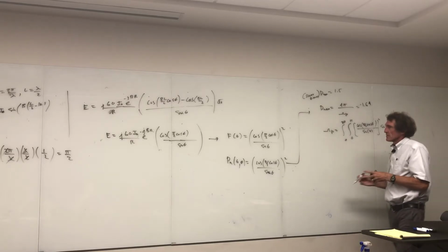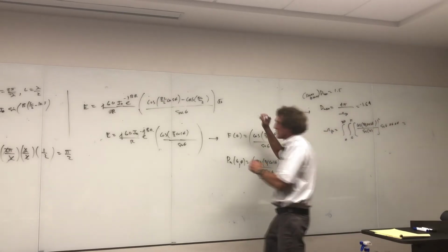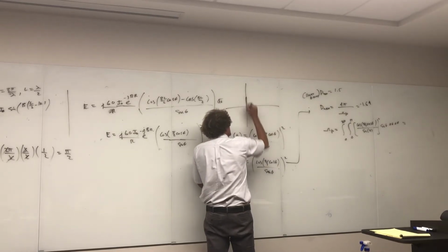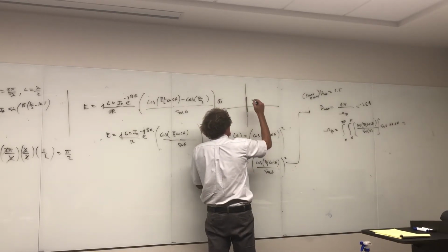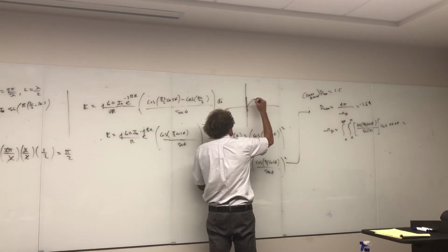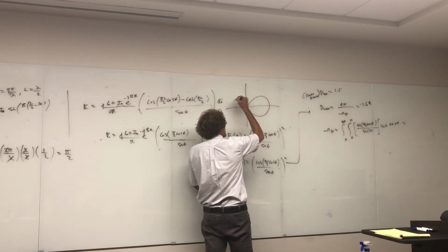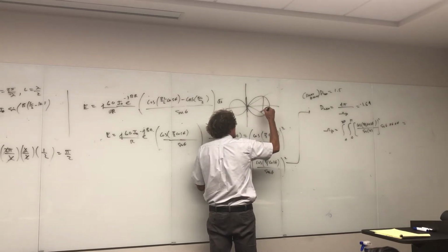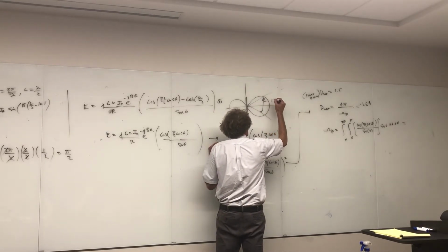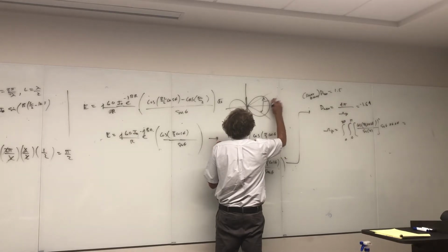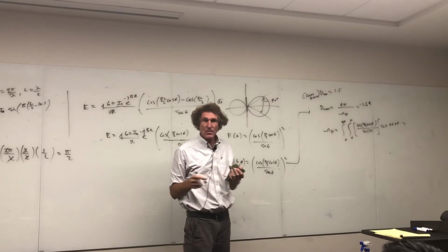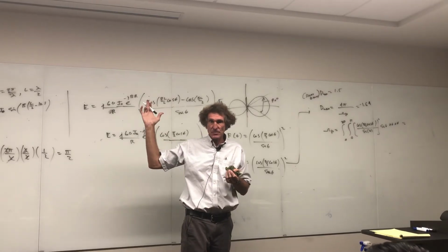As a matter of fact, if you looked at the patterns, and I'm going to try to draw these here, if we talked about an antenna oriented in this direction, and it was a short dipole, you would have this. And you would basically have a beam width of 90 degrees. Remember? It's from 45 to 135, or a beam width of 90 degrees. How many remember that for a short dipole?